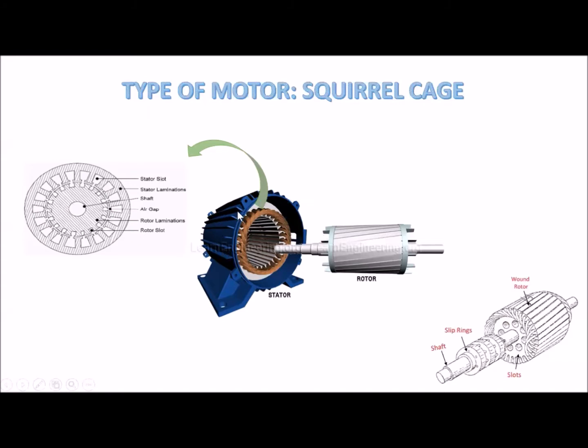The stator over here is responsible for generating a rotating magnetic field in the induction motor by three-phase alternating current. As you can see over here, this is the stator lamination. Stator laminations are used to reduce the losses, which are eddy current and hysteresis losses that occur during operation. For the rotor, it has a series of rotor slots. These rotor slots are composed of punched laminations stacked together and provide a space for the rotor winding.